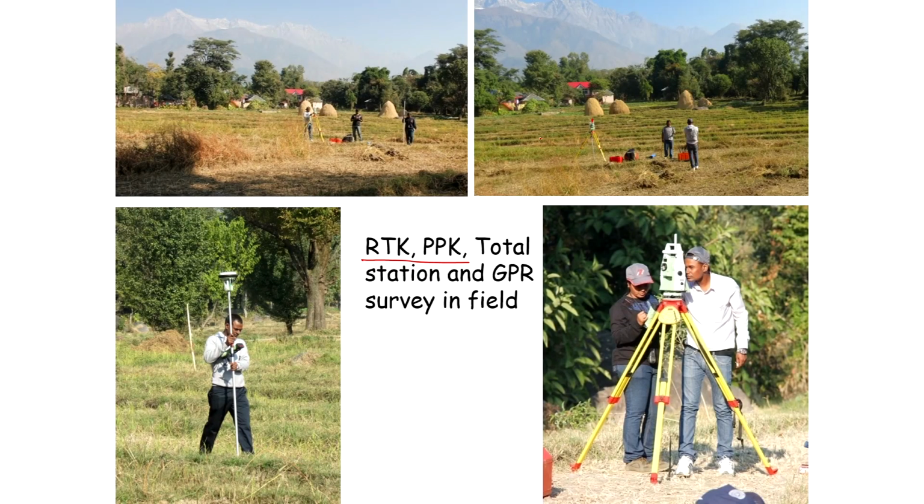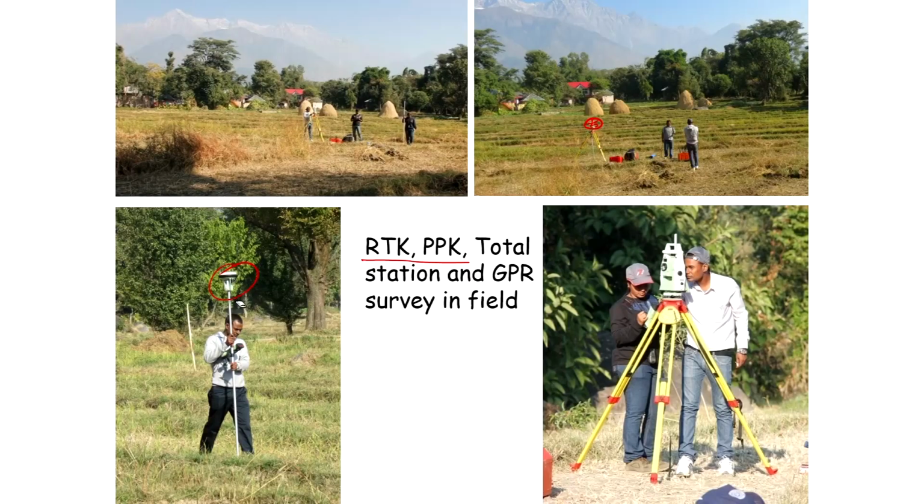So you just set up one GPS over here, okay, and another you put as a rover here, and you keep moving, depending on what time frame you need and how many seconds you want to collect the data. So every 50 seconds or 1 second you want to collect, or 1 minute or so, but usually we keep 50 seconds or so, so we can have precise data.